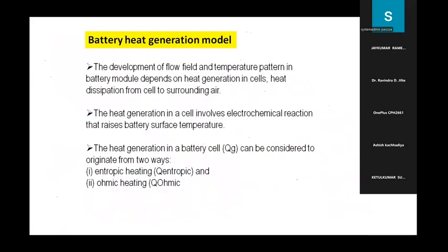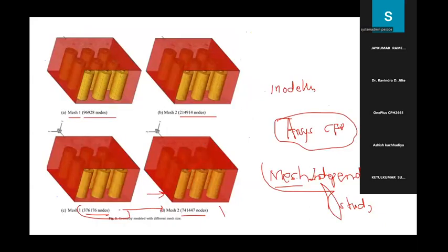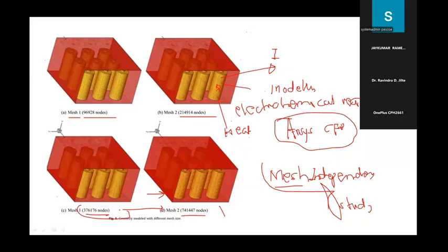We need to understand physically, there are two things. When we connect this battery and withdraw the current, at that time there will be some kind of electrochemical reactions. For example, in this battery there will be an electrochemical reaction. Now these electrochemical reactions will generate heat. If you have physical setups, you can attach thermocouples over here and measure the temperature as well as the heat.